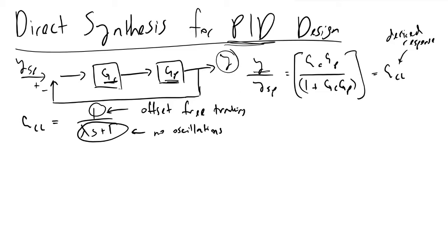And so now that we've done that, there are some multiple cases, but as an introduction, we will consider minimum phase dynamics. Minimum phase dynamics, which implies that we have no right-hand plane zeros. And so what right-hand plane means is it refers to the real part of the zeros, which are the roots of the numerator in our process